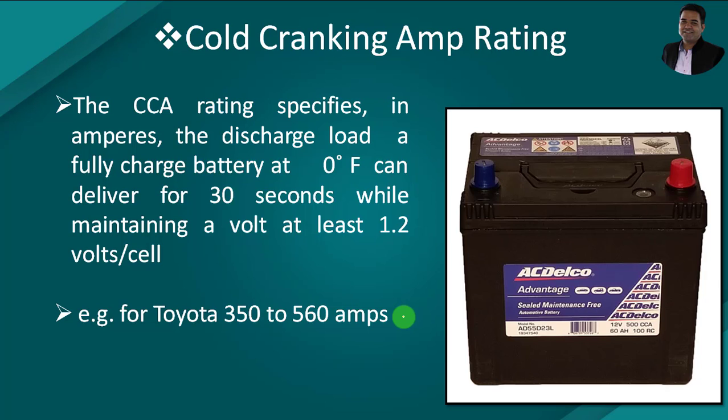So the cold crank ampere rating indicates the amount of amperage that a battery can deliver at 0°F temperature. For vehicles operating in territory where the overall operating temperature is quite low, in such cases we need to focus on the cold crank ampere rating.